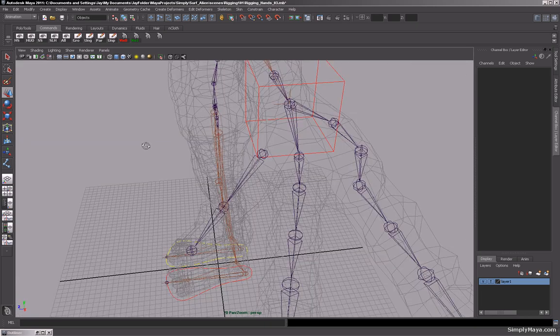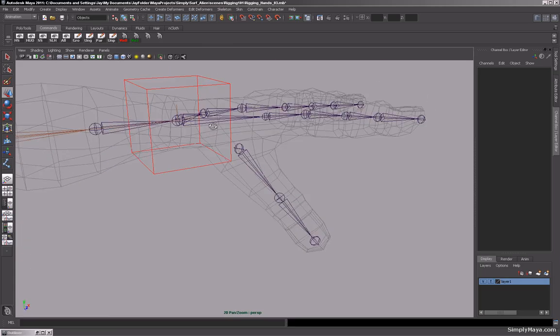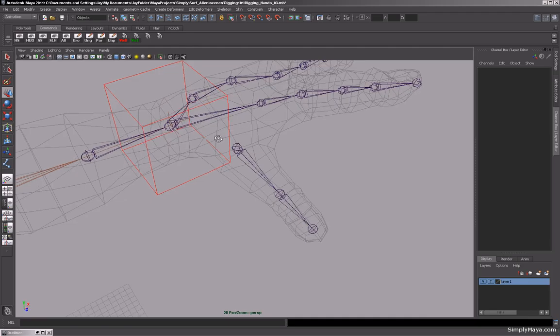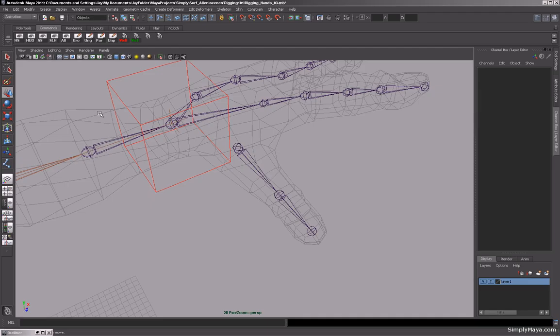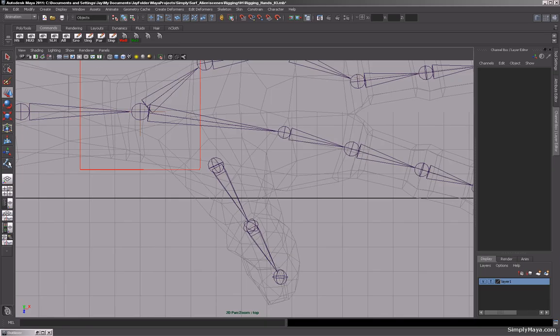Okay, so what we need to do now is I'm just going to add in an extra joint, just one there, because the thumb is a bit strange. So we'll have a joint there, and we should be pretty good to go. So I think just one just in there. So if we just jump in our top view, and we'll place it about there. Okay, so about there. So we'll call that thumb palm. Hit enter, and again we'll hit thumb palm, or LT underscore thumb palm.